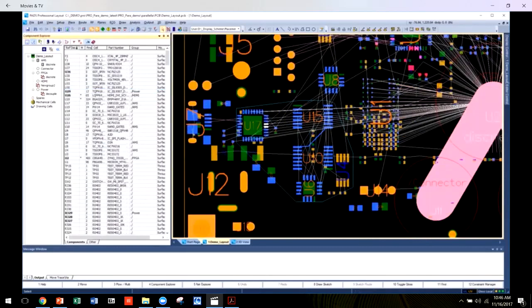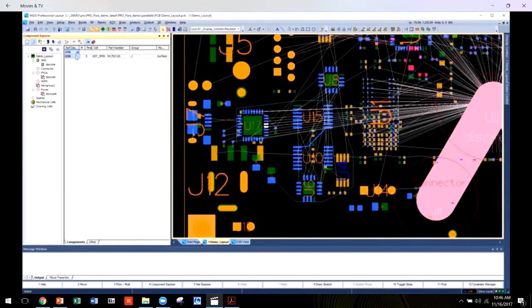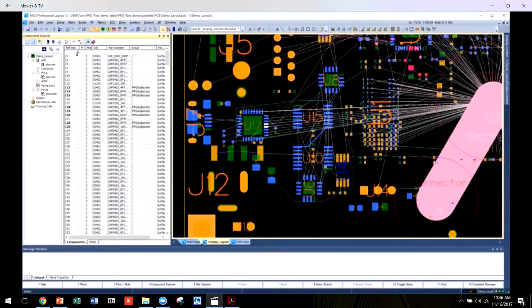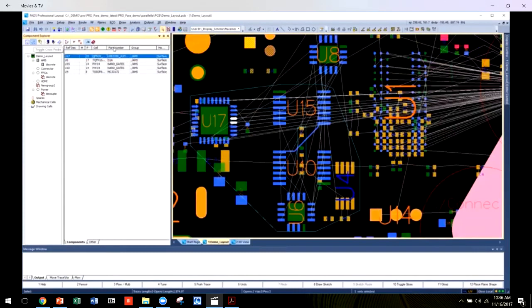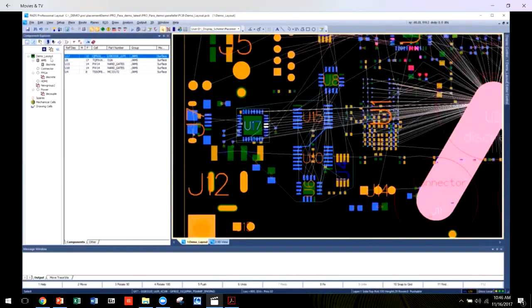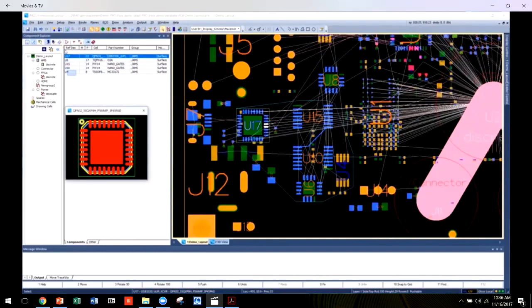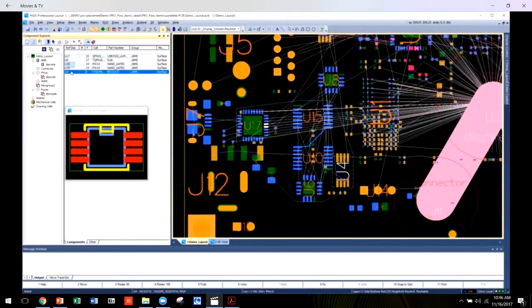With each planning group, including the master board group, a list of components is displayed that can be searched, sorted, and customized by property, allowing you to organize and strategize your placement of individual components and planning groups. You can enable cross-probing within Component Explorer and the board to quickly find components already placed. The selected component cell can be previewed before placement in order to guide your placement strategy.